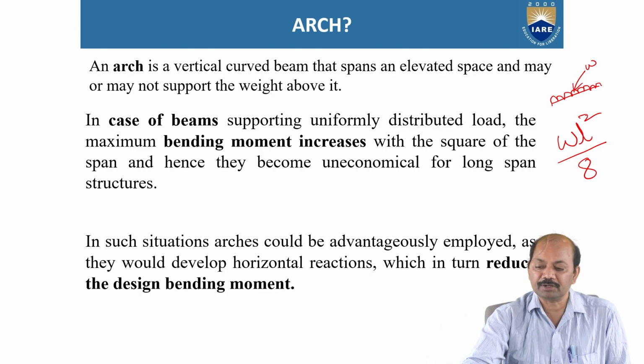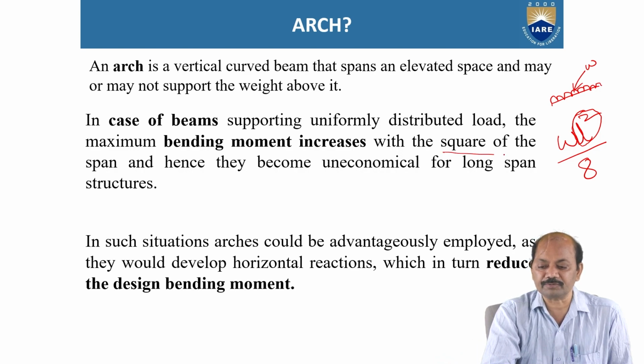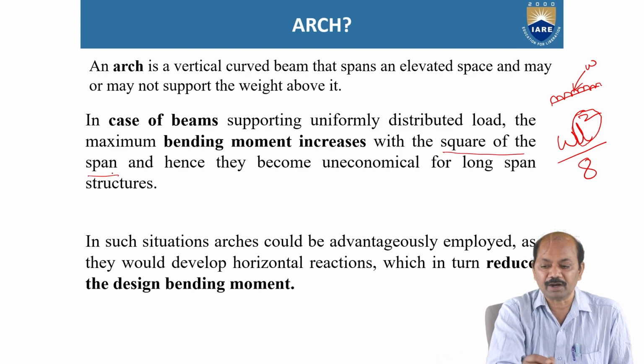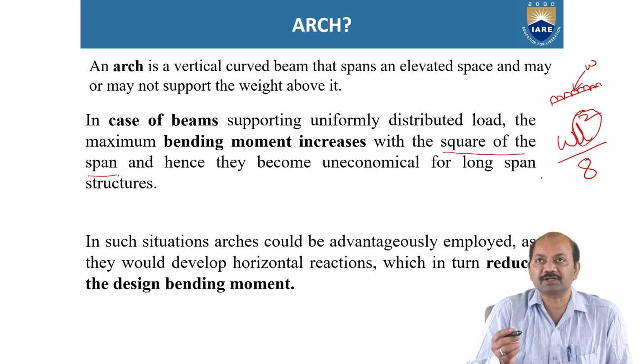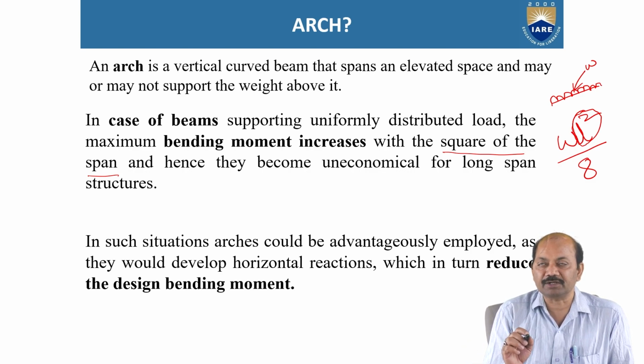The maximum bending moment increases with L square in that formula, and hence beams become uneconomical for long span structures. The reason is, as span increases, bending moment increases.